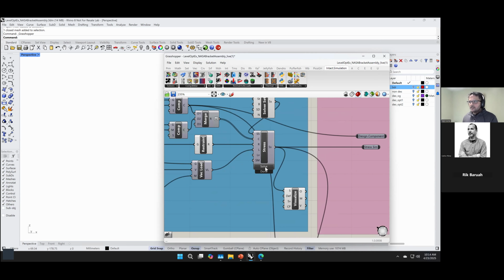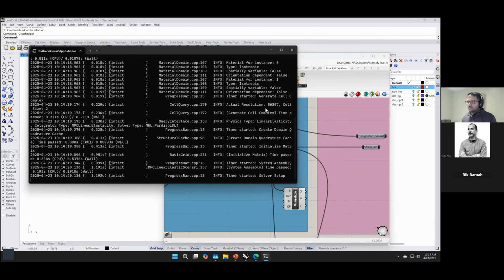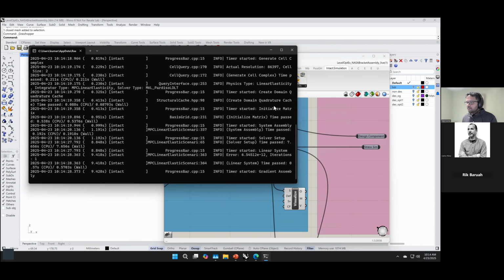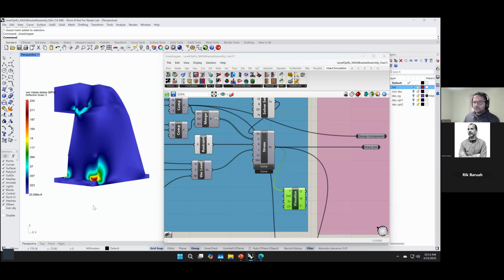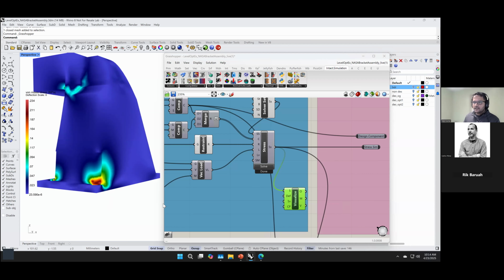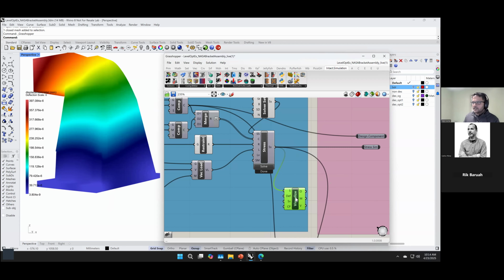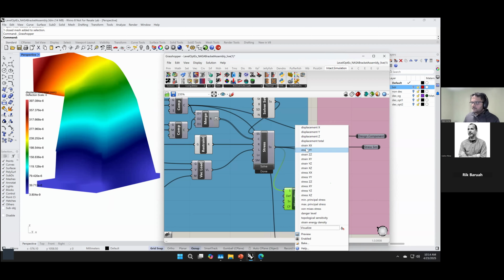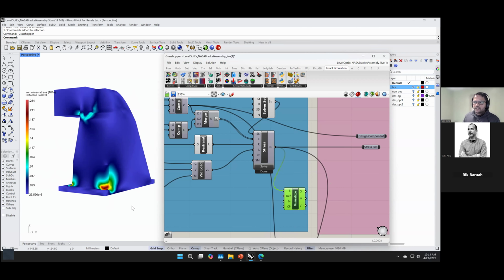So once all of that is done, you just run the stress simulation. I'll rerun this. It's very quick. As you can see right here, the logs show almost 100,000 elements in the simulation, and it solves within seconds. Almost done. Yeah, it's done. And this is now results on the original geometry. So this is how the stresses look like. Von Mises stress, as you can see, and then we have a range of quantities you can visualize. So what's the total displacement? What's the strain, max principal strain, and all that typical FEA quantities you want to see.